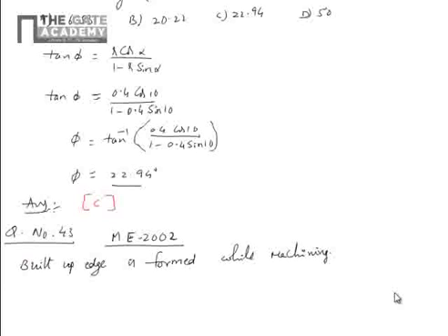When you use slow speed, they will have time to stay there. So the answer is: while machining ductile materials at low speed. The answer is B.